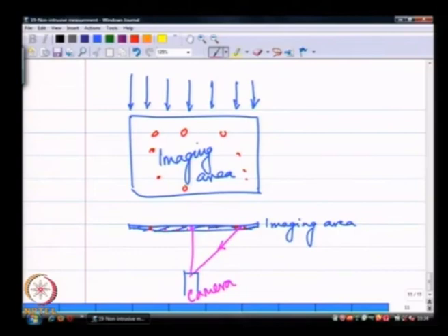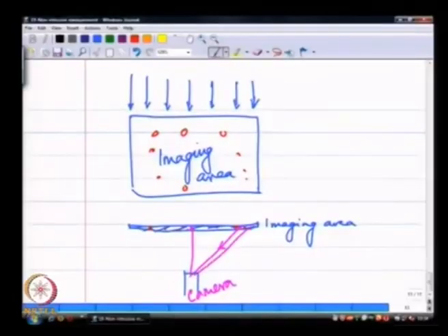Okay, so, if my field of view is much larger than the camera aperture, which is always the case, it is very rare that you are imaging at 1:1 or less than 1:1 magnification in a typical PIV application. So, you are really looking at a fairly broad region in the spray, and so this typical angle may not be as large as the schematic indicates, but it is surely not small, it is surely not 0 degrees.